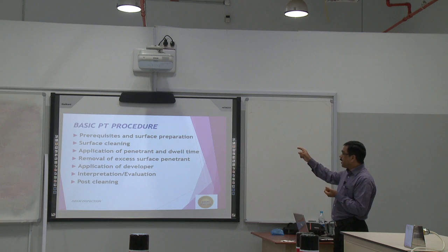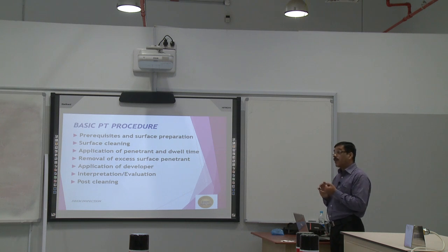When preparing the surface, we should take care, because some surface preparation methods are not allowed in penetrant testing, like power brushing, sand blasting, and grit blasting, because there is a chance of smearing these discontinuities. By sand blasting, a small crack opening may get smeared and covered.